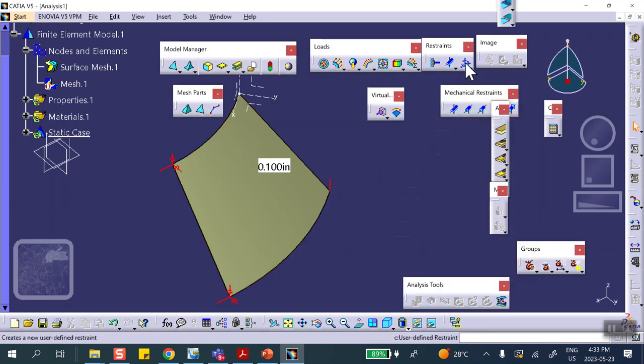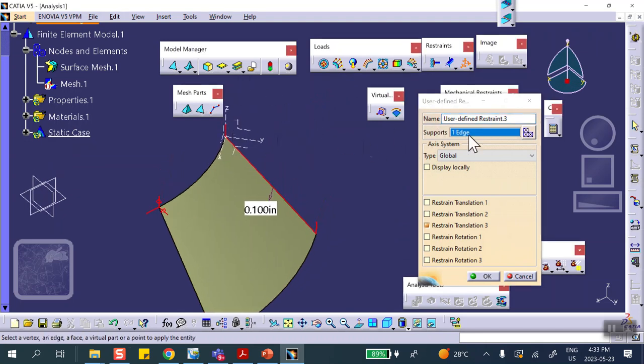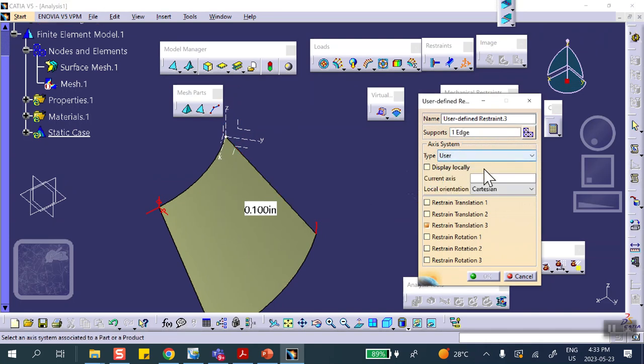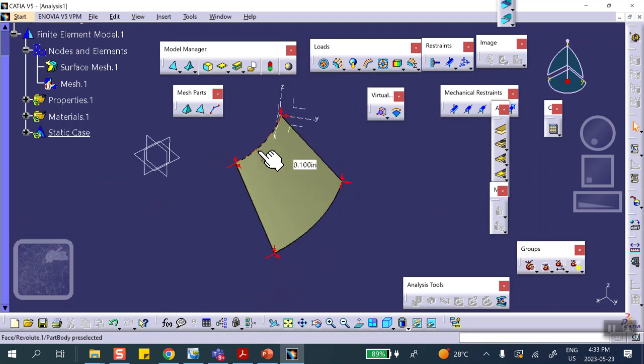And then the back one is on the YZ plane of symmetry, not of the global one, but the user one. And it asks where the coordinate system is. It's this one. And if it's in the YZ plane, no displacement in X, rotations opposite. And we say okay. All right, we're almost done.